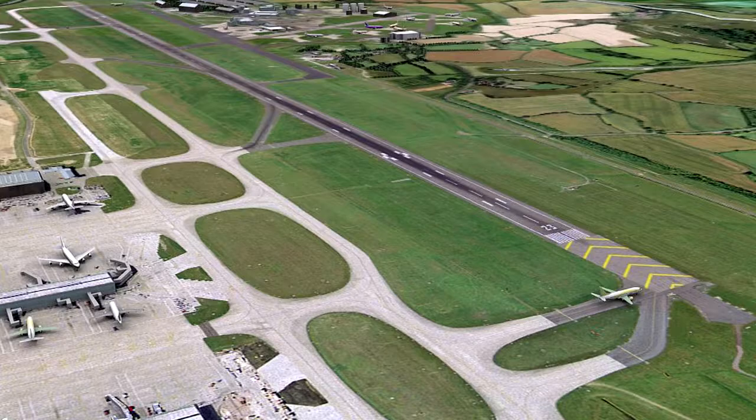A stopway may be an economical substitute for what would otherwise have to be provided as paved runway to meet takeoff field length requirements of some aeroplanes. When comparable field lengths are required in each direction, it will be necessary to have a stopway at each end. Stopways cannot be used for any other purpose than bringing an aeroplane to a stop after an aborted takeoff. When lining up, a pilot must taxi to the threshold and start his takeoff run from there.